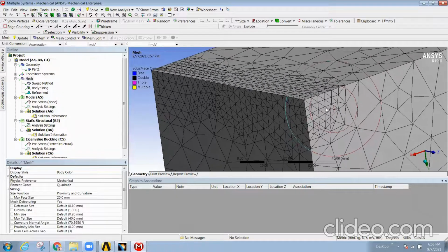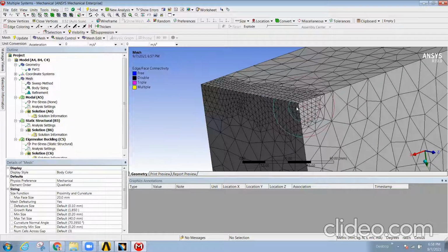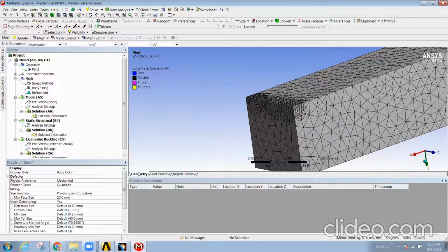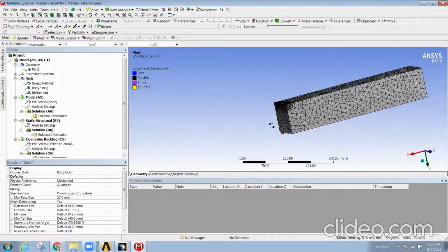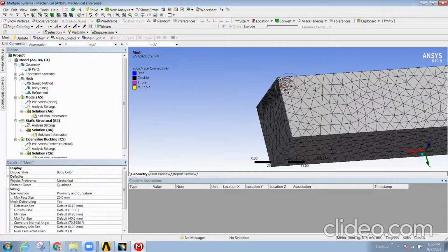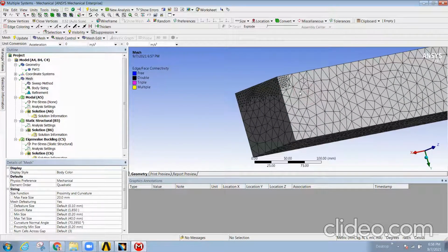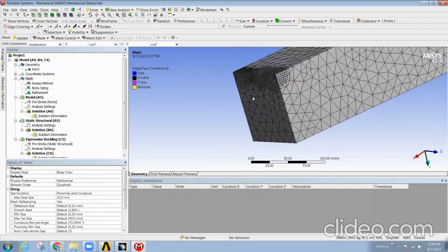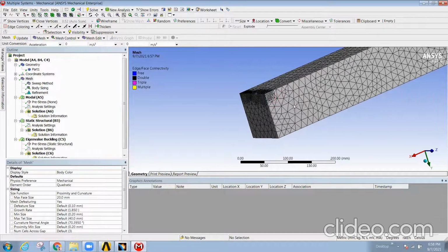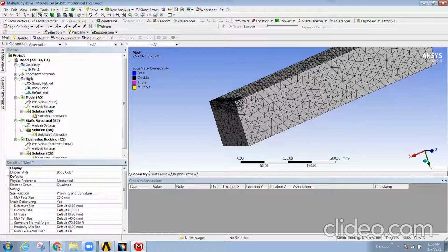You can see clearly. If I take a point edge also, sometimes what happens is one surface or one curvature is a very critical location, but for that critical location we can't change the entire mesh. Considering my tooling, this is a tool, one edge is very important to us to know the transfer of load as well as heat transfer from the cutting edge. So at that moment you can use this kind of refinement and do the mesh so that it will capture more load over the edge itself, or on the surface itself. So this is a refinement.